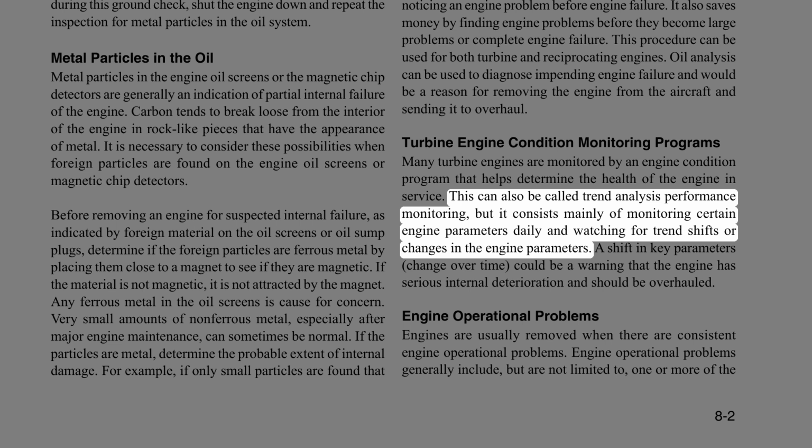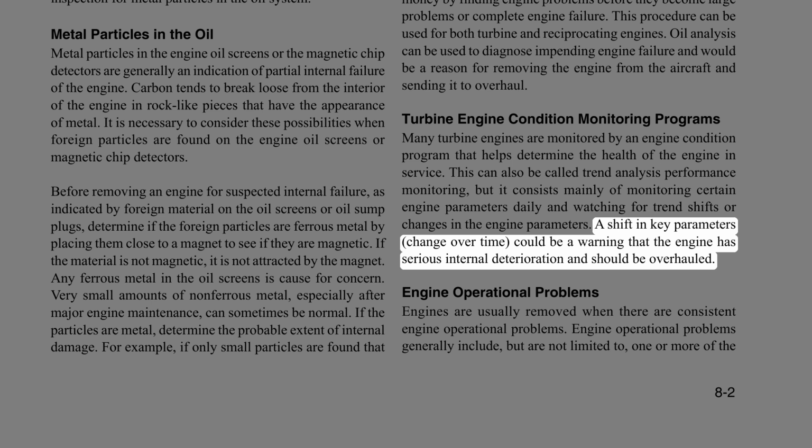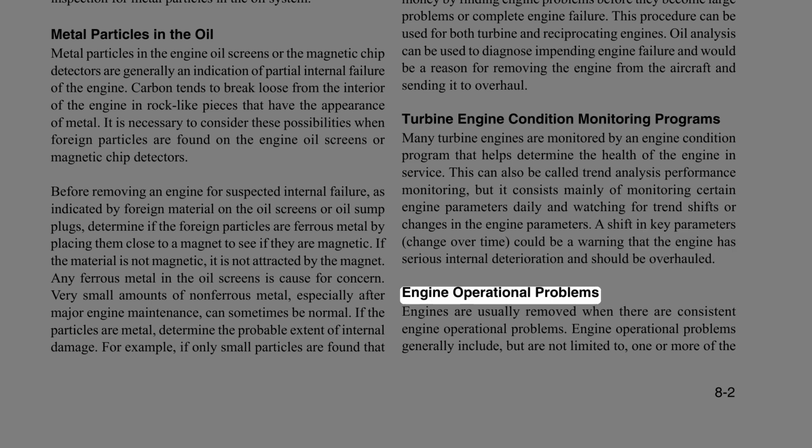This can also be called trend analysis performance monitoring, but it consists mainly of monitoring certain engine parameters daily and watching for trend shifts or changes in the engine parameters. A shift in key parameters, change over time, could be a warning that the engine has serious internal deterioration and should be overhauled.